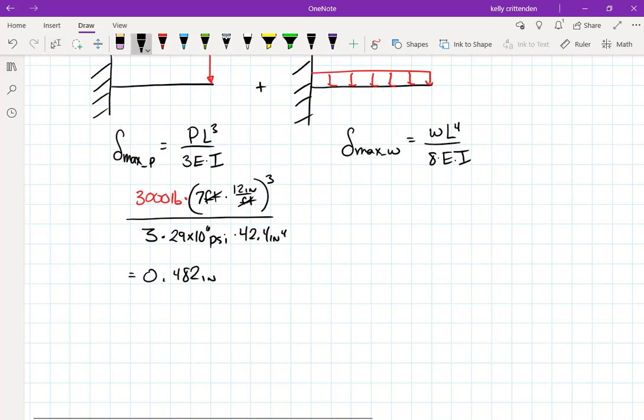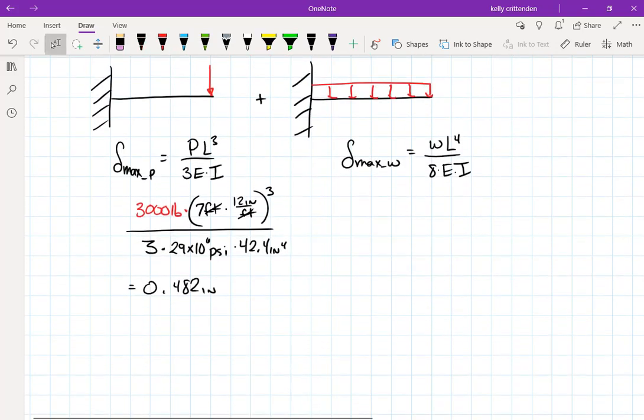This one, you have to be a tiny bit careful here. So W is 500 pounds per foot. And so it helps if you actually write out your units instead of just put the numbers in there, because what people will a lot of times do is, oh, I got to convert that over to inches, so I'll multiply by 12. But make sure you actually want to cancel out feet, so you divide by 12. W is the same as it was before. Well, I guess I just violated what I just said. Put your units down.